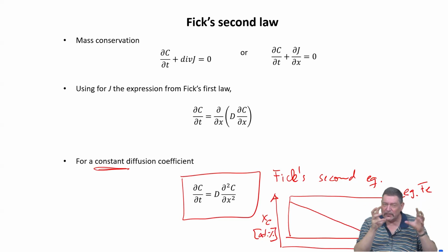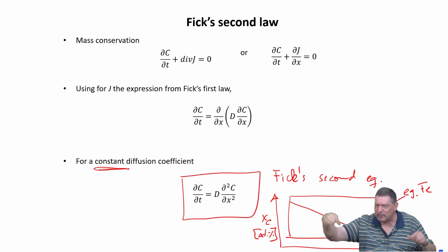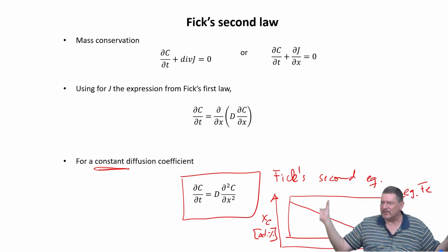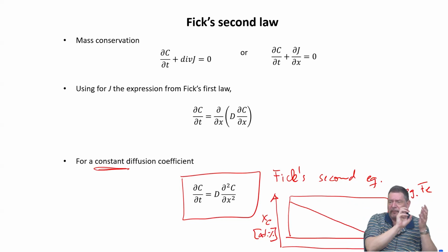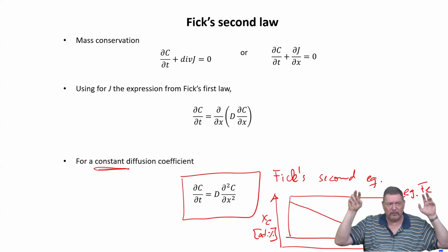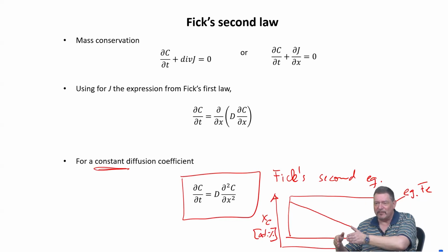Also, there will be some strain putting carbon into the octahedral sites, so the neighboring octahedral site probably is affected and is not as probable a site as if there is no one occupied around it, right? So going from one side to the other, making a diffusive jump, depends on how much carbon is in there. So diffusion will change the diffusivity.